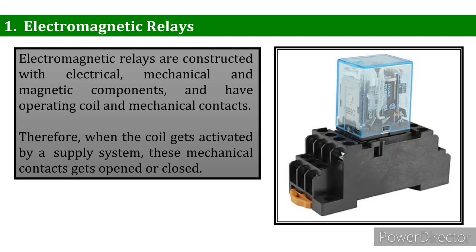The working principle of electromagnetic relays is not complicated, and of course it's not new, but it operates mainly according to the principle of electromagnetic induction. When the power is switched on in the low voltage control circuit, the current goes through the coil of the electromagnet to generate a magnetic field. Then the armature generates a suction force, making the movable contact and stationary contact touch.